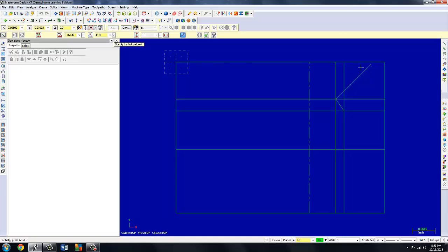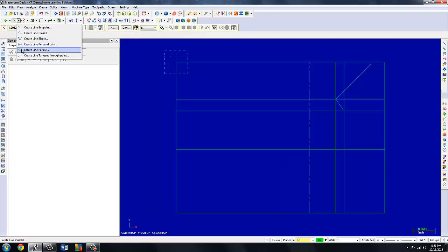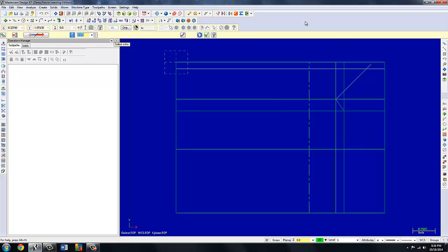Looking at my drawing, it looks like it cuts off at 3.475. So I'm going to check out of that and go back to parallel lines and put in my 3.475 dimension, and that comes off this bottom and it's in that direction. Now I can trim my 45-degree angle to that as well.